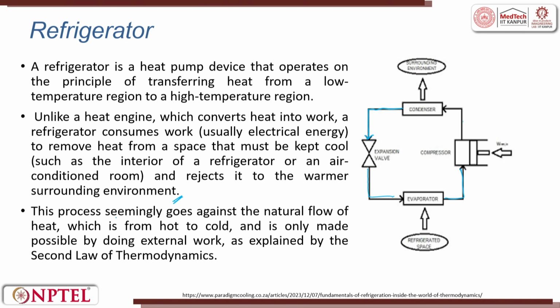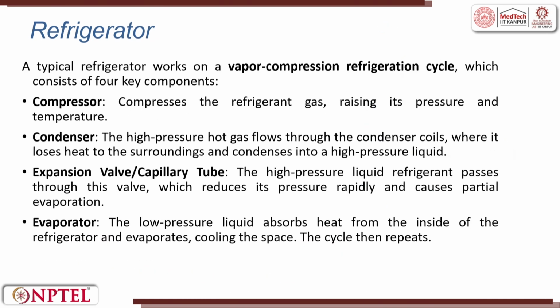This process seemingly goes against the natural flow of heat, which is from a hot body to a cold body. Now, you are moving heat from a cold body to a hot body. This is only made possible by doing external work, as explained by the second law of thermodynamics. So, this is how a refrigerator works. A typical refrigerator works on vapor compression.